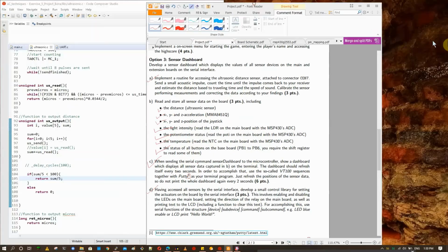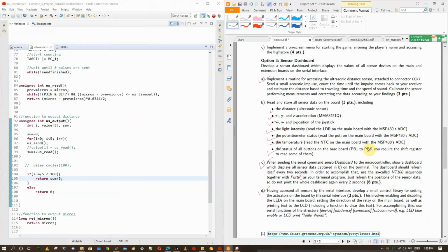Going back to the project questions, one important feature to mention about the first question is that the range of the ultrasonic sensor was limited to around 20 centimeters, and the accuracy is a little less, so it gives proper distance for a large object, though with some inconsistency. But if we place a softer object, like a sponge or a rubber, it fails to detect it very accurately. So the range comes down to around 10 centimeters for softer objects.